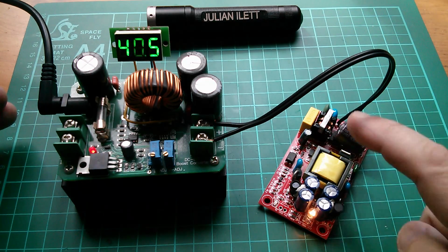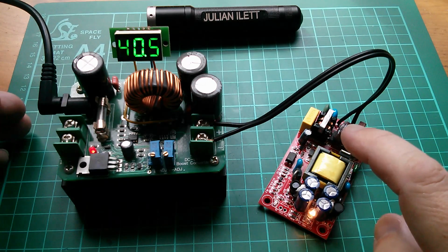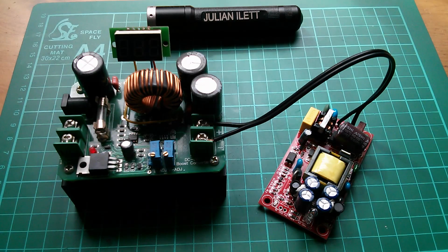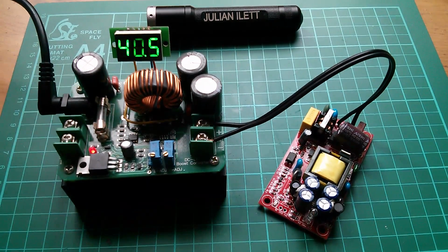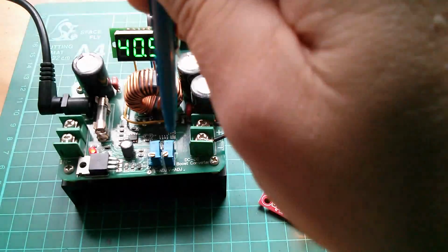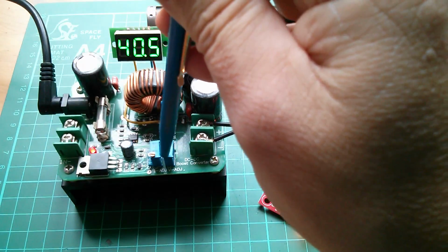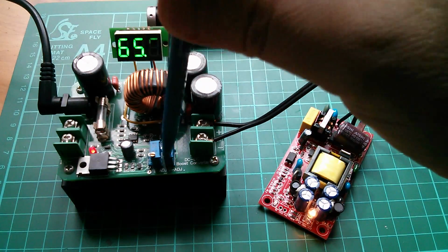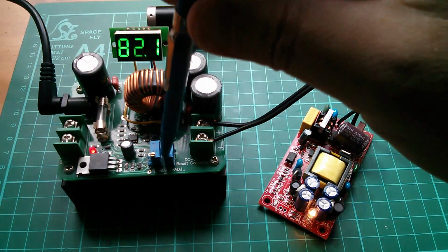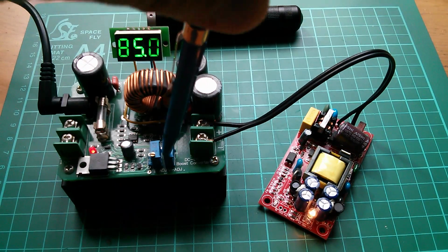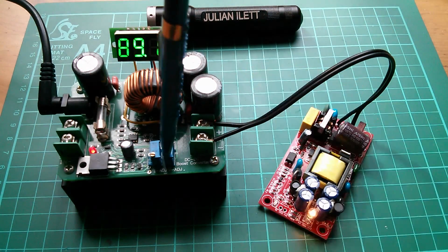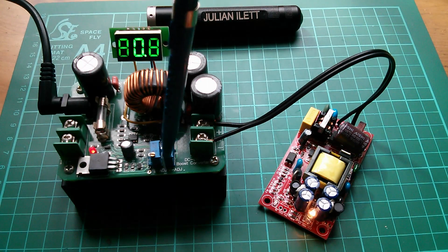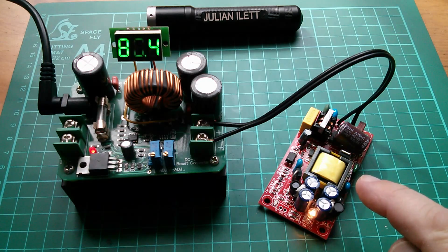I'm not sure how reliably this is working. Of course, it may not be working very efficiently like that, but let's wind this up to the full 80 volts. Right, let's plug that in. I found my Bourns trim pot, so V adjust. Yeah, that's going up. 60, 70. This actually does go a lot higher, I found, but the caps, I can't remember what their rating is, so perhaps I'll leave it at 80 volts. But yeah, at 80 volts, certainly this thing works.